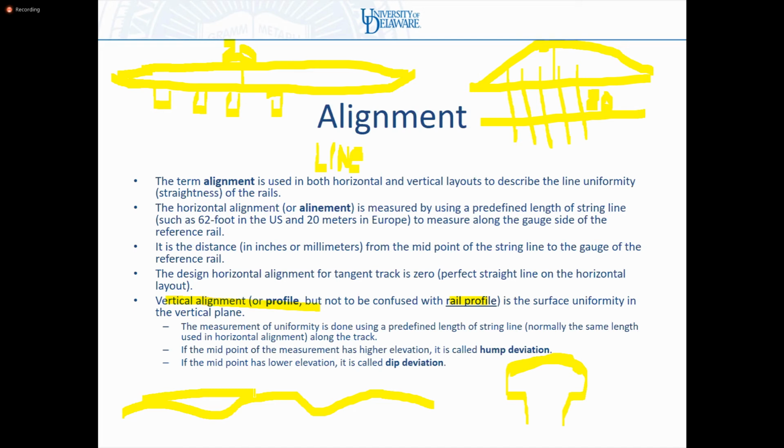Most track geometry engines, if you go to Israel Rail Standards, for example, are defined in terms of 10 and 20 meter chords. In fact, I think I have some slides a little later showing you that. So when you take an inertial system, you mathematically draw a point to a point, and then you can pick up a hump very easily. So I can now measure a 20 meter hump very easily if I have an inertial system.